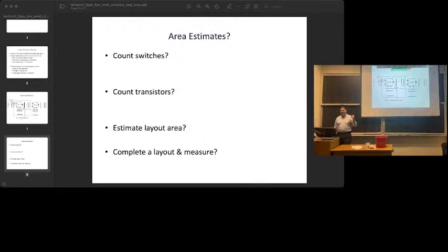Does that make sense? So in that case, where you use standard cell ASIC tools, you can get an answer pretty fast. Okay, there are tools that basically can automatically set up the FPGA netlist essentially, and you can then get an answer. It still takes a while for the ASIC tools to run, but you can get an answer in maybe a day or a week. Whereas what I'm going to show you to lay out by hand, it will take you probably months. But you will get an answer that is maybe 2 to 3 times more dense and twice as fast. Does that make sense?